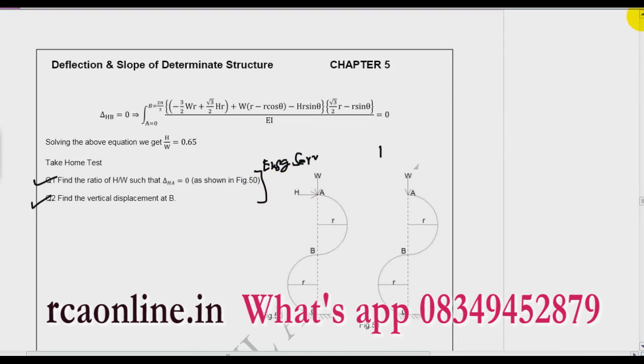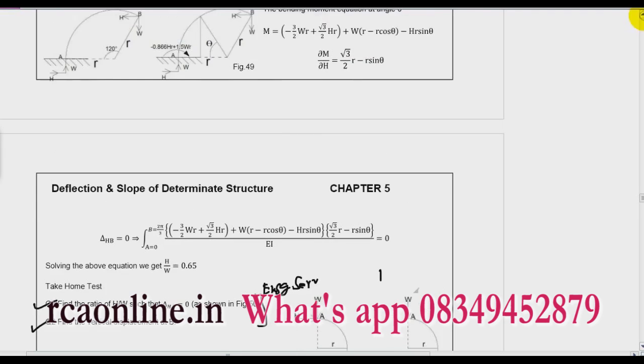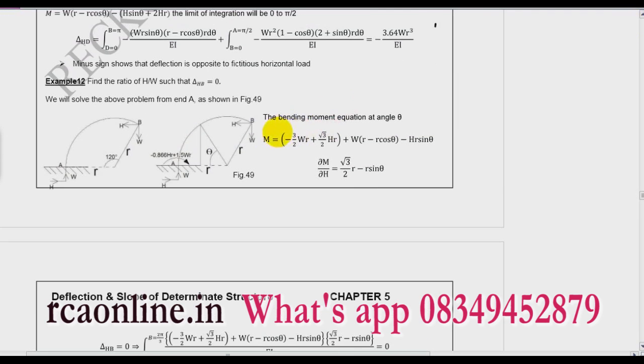I want to discuss one problem, but again this is a very complex problem and very time consuming. So what it says, now the angle is 120 degrees and you have been given two loads, horizontal and vertical both. We have to find the ratio of H by W in such a way that delta HB is 0, meaning the horizontal deflection at B should be 0. So what should be the ratio of horizontal to vertical load?